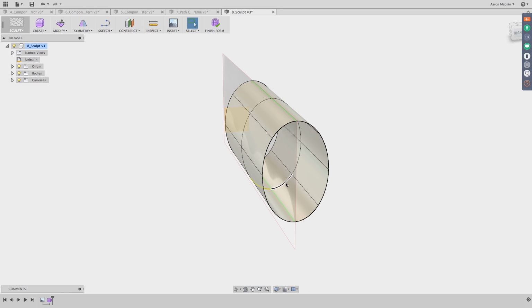So I'm going to select just a single edge and right-click. When I do that, it gives me this ability to do things like insert edges, to slide edges, to bevel edges, or unweld edges. And then I'm going to select insert edge. But one thing I want to do here is I want to show you what's going to happen. Although I only selected this one, because I have symmetry turned on, it's going to insert another edge on this side, although it's not previewing it currently.